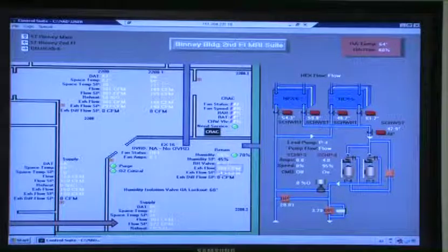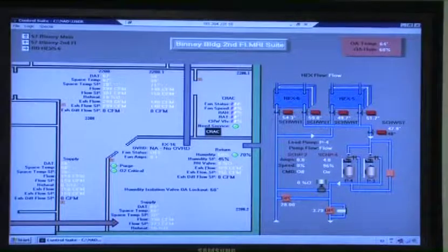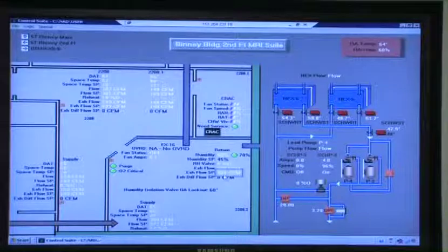Your assumption on the dampers is that if the dampers don't move, the fan's not going to start. Right. So there's your assumption that the damper's opened, because if the fan is running, then the damper's opened. If they're not open, then the fan isn't going to run. That's another way to look at it also. I want to make sure, that's a good point. This should say return flow instead of exhaust. So return flow should go to 0, right? That's a good point.